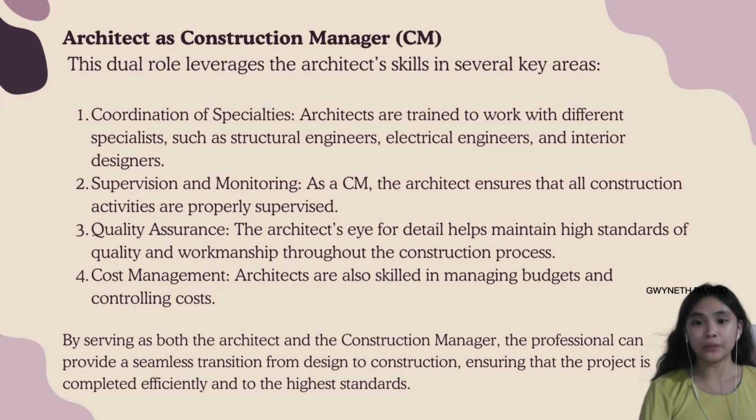Second, supervision and monitoring. As AECM, the architect ensures that all construction activities are properly supervised. This includes regular site visits, inspections, and meetings with contractors to monitor progress and address any issues that arise. Third, quality assurance. The architect's eye for detail helps maintain high standards of quality and workmanship throughout the construction process. They ensure that the work meets the design specification and industry standards.